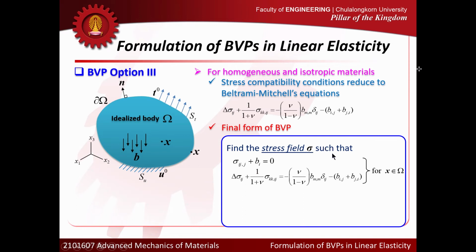These two sets of equations have to be satisfied at every point x in the body. They cannot be satisfied at just some points in the body. To be the solution, stress has to satisfy these two sets of equations at every point inside.